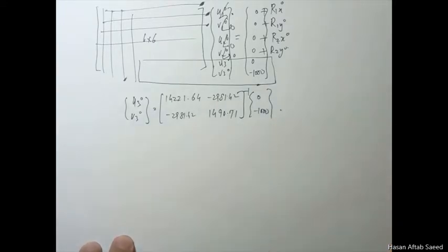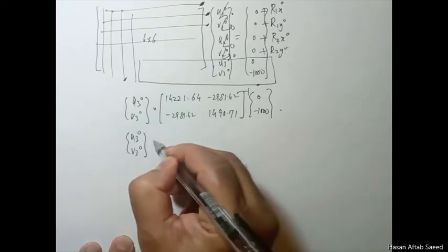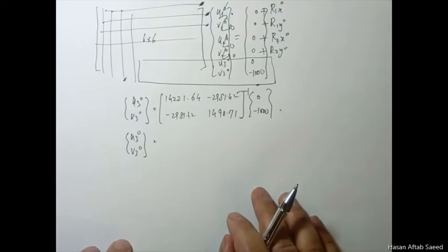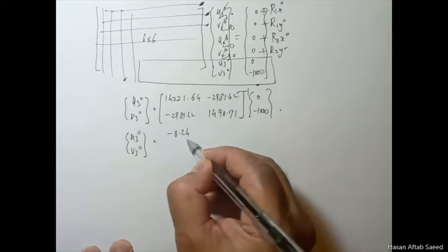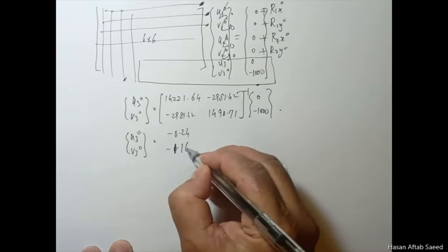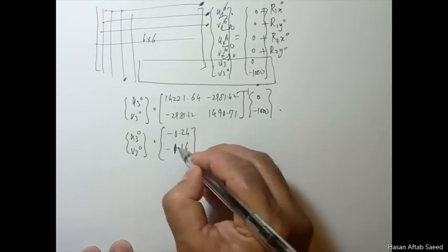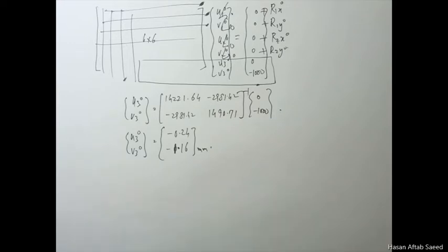It's very easy to take the inverse for this, and for u3 v3 your calculator will do it. You can also do it yourself without using the calculator. So if you do this, you get 1.16, and because we made sure that our forces were in newtons and the stresses were in MPa, this has to be in millimeters.